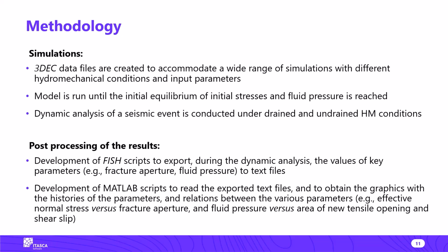Several numerical simulations were conducted. 3DEC data files were created to accommodate a wide range of simulations with different hydromechanical conditions and input parameters. So stressed fluid pressure conditions at 500 meters depth were considered, and the model was run until initial equilibrium was reached.